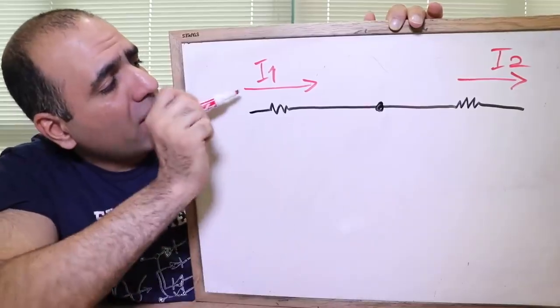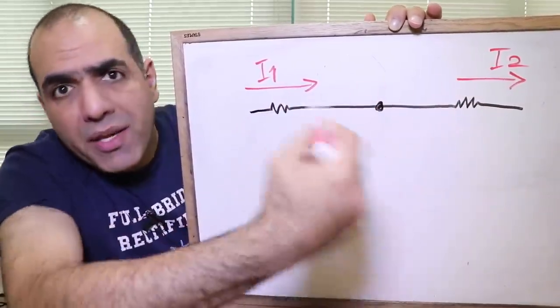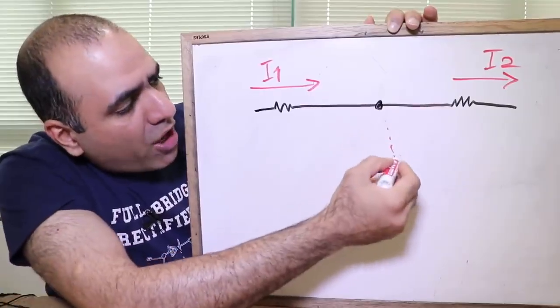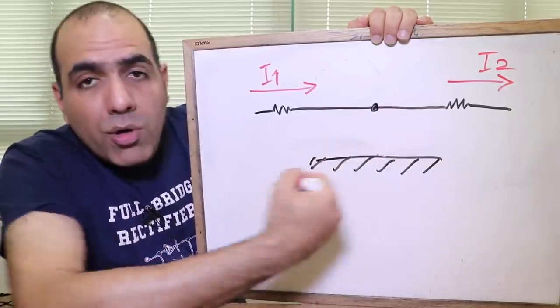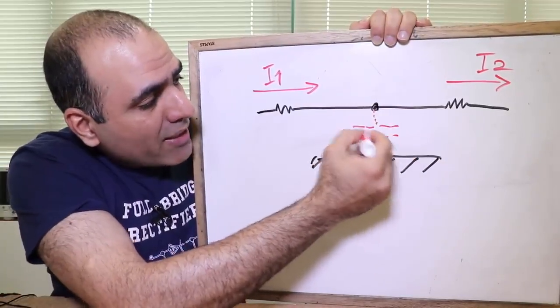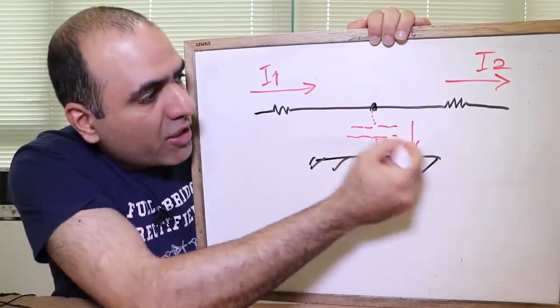And imagine you have AC current going into a node and going out of the other side, and you expect both to be equal. You measure and they're not. This means there must be a third current leaking out somewhere. But where? Maybe your wire is running too close to ground, and that creates a stray parasitic capacitance between your node and ground that you didn't account for and is sucking the current away.